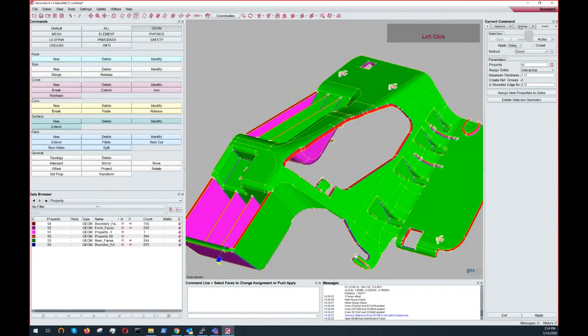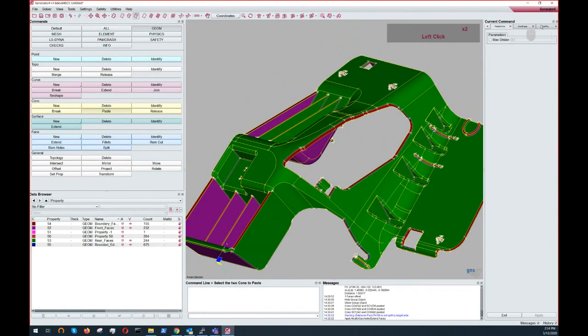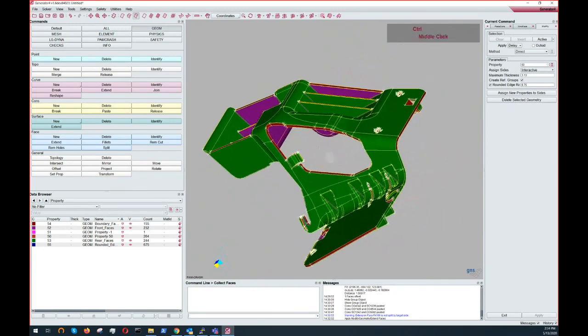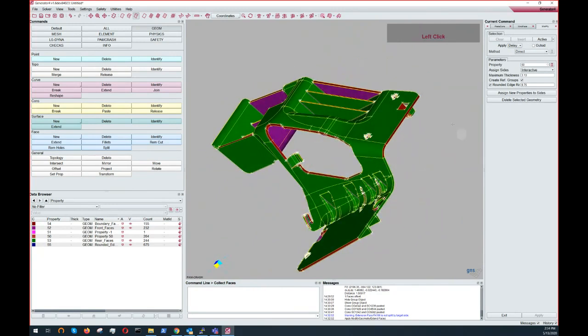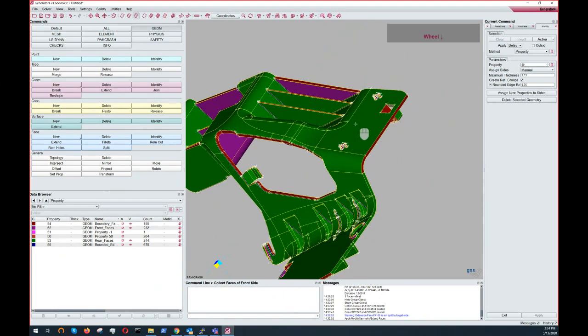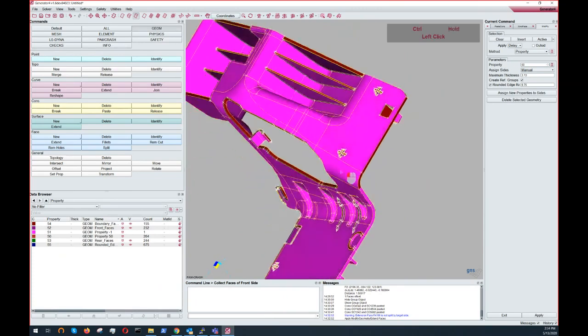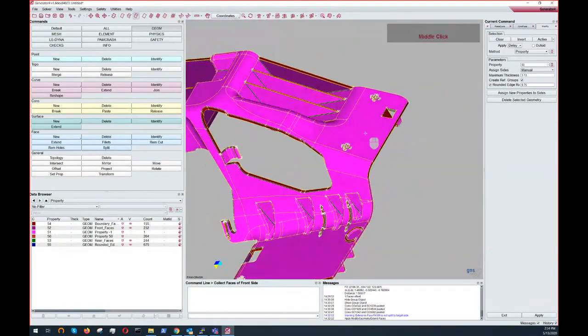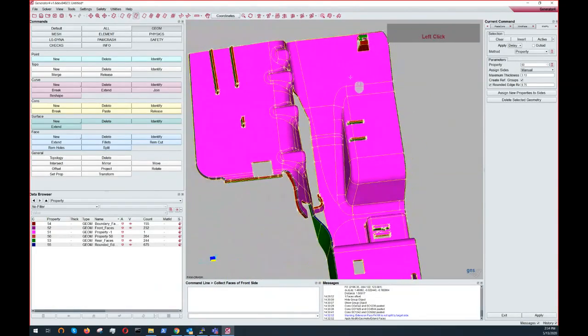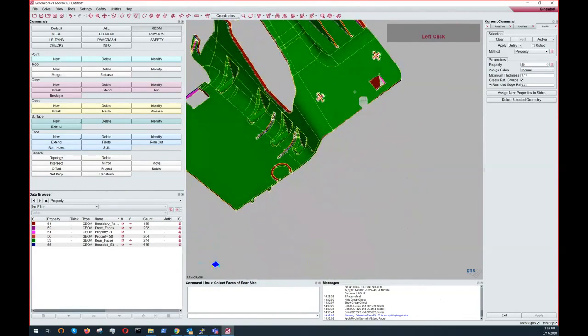So suppose I enter again the command and I want to select them, and now I could change to manual and just select by properties. So I could select this one that was previously found by Generator as front. So I will select this one and make it the front selection, right mouse. Now I will select the rear.